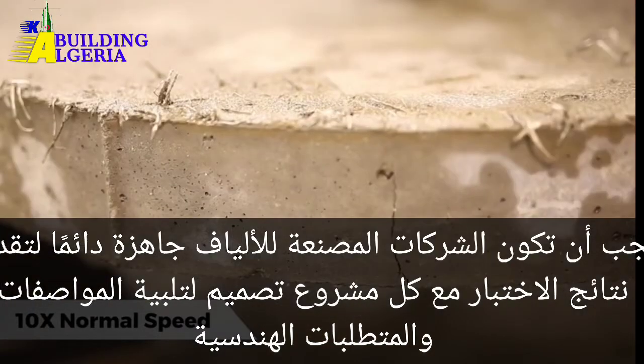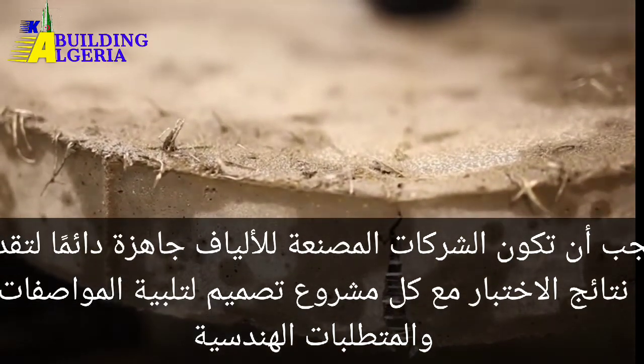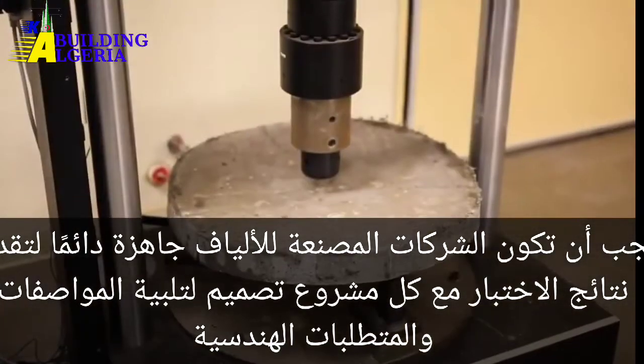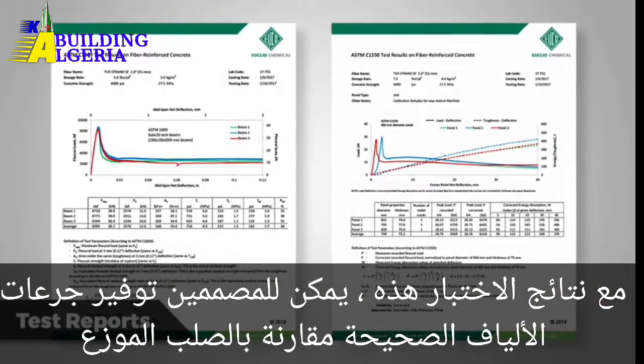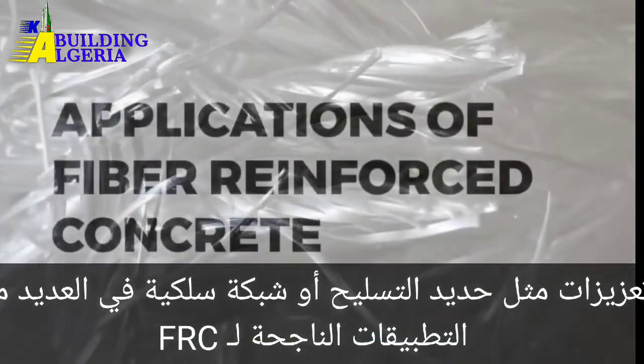Fiber manufacturers should always be ready to supply testing results with each design project to meet specification and engineering requirements. With these test results, designers can provide correct fiber dosages in comparison to distributed steel reinforcement, such as rebar or wire mesh, into many successful applications of FRC.